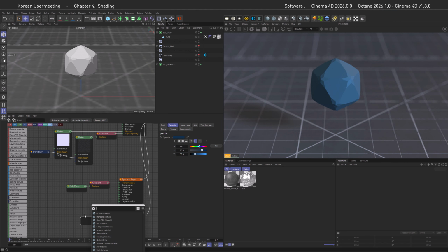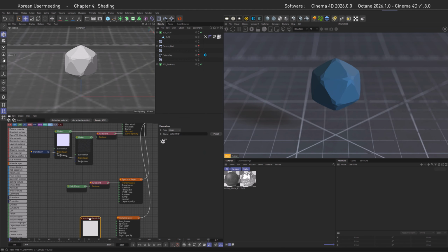As with the flakes, we need some sort of transparency map, and this is where the attribute comes in, as we are going to use our vertex map in there, so we need to set it to float and drag our vertex map in the name slot. And let's turn on solo mode to show if everything's working.